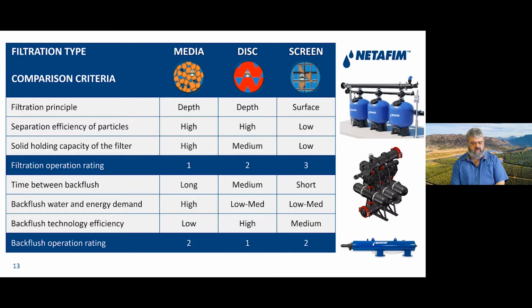The last one is the backflush technology, the efficiency of the technology. And this is now not the filtration, but the backflush. So although the media filter has the highest efficiency for filtration, when it backflushes, it's not that exciting, because you must lift the whole sand bed. And if you don't do it correctly or often enough, then you can create problems.